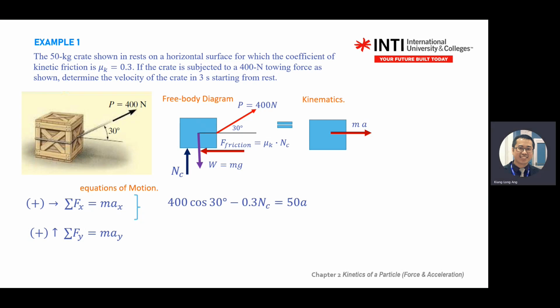Normally, the mistakes will be the negative sign. You'll forget. In your free body diagram, you give it correctly, but when it comes to your analysis, somehow some students will not make the friction negative. Just be careful on this.